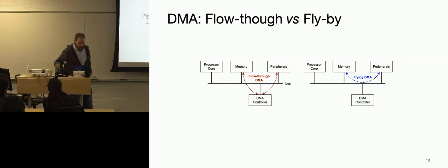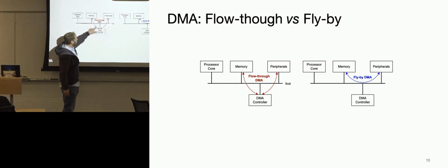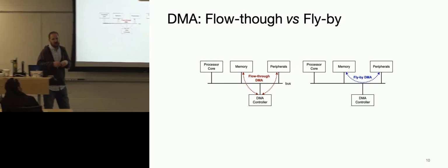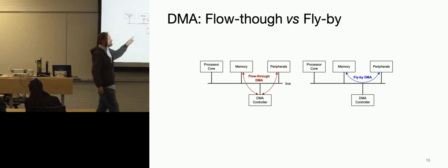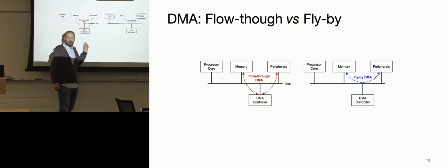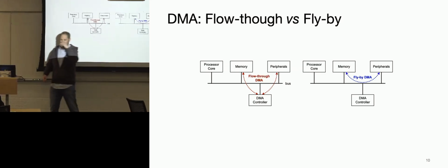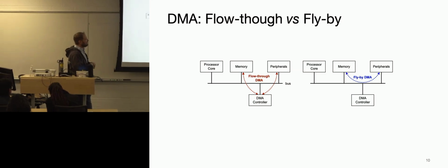So there are 2 general philosophies to get this done. You have a DMA controller, which is on your bus, and this acts essentially like a second core. You don't get to write code for the second core, but you can configure it like a peripheral to do a task for you. That task would probably be like, go to this memory address, or maybe on an interrupt, go to this memory address, get some value, and put it into memory at this memory address. And you can set it up to do it circularly, or like a ping pong buffer, or just from one point to another point.